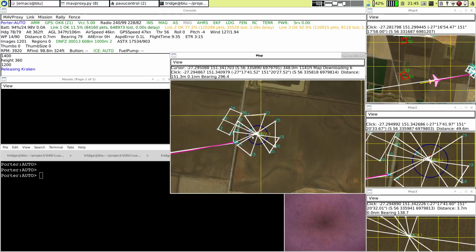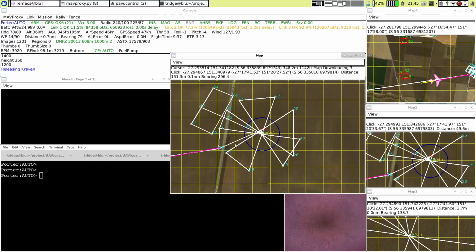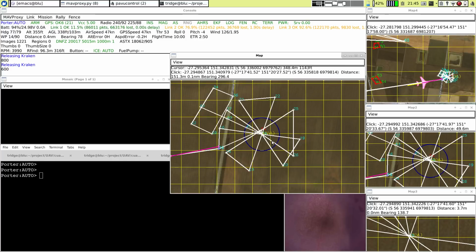All right, so you'll notice that it's a sort of cloverleaf type pattern, the search. That's to reduce the systematic errors you get from small amounts of roll and pitch error in the aircraft and timing delays from GPS and timing delays from the camera. By approaching the target from all directions and averaging the positions, we can get a very accurate georeference. And we typically get about 1.5 meters or so in our georeferencing for the landing position. So it's flying this sort of cloverleaf pattern.